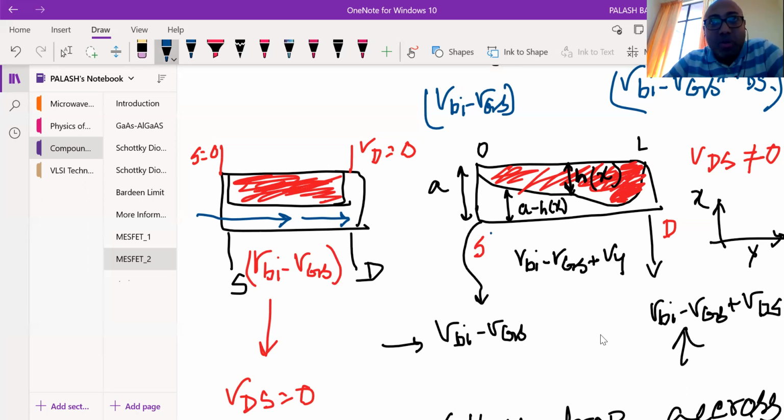These things you can explain with a series resistance. So the resistance amplitude is increasing. On the source side there is no problem because you have enough channel thickness, so my resistance is low. But whenever you go towards the drain side, my resistance is high, and that is why I have given a large amount of resistance, right? Now your current is flowing through that.